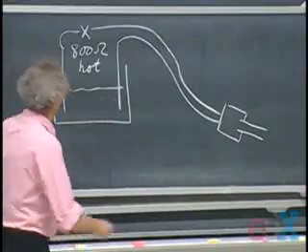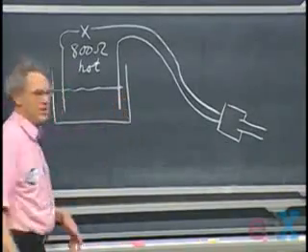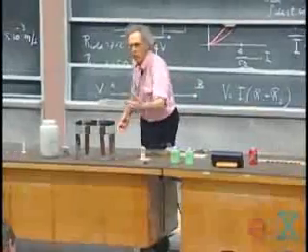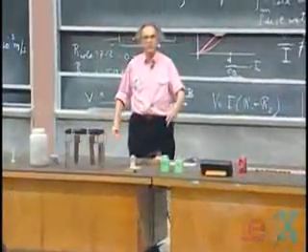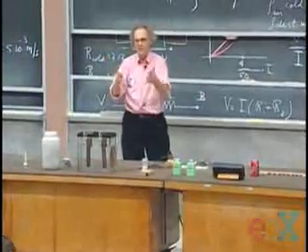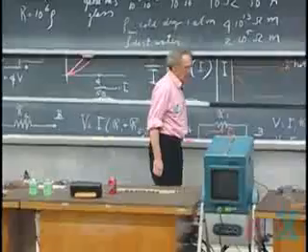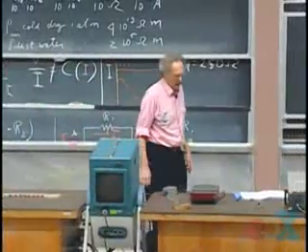You can calculate what this resistance is between the 2 plates. That's easy, you have all the tools now. If you know the distance, it's about 20 centimeters, and you know the surface area of the plate, because remember the resistance is inversely proportional with A, so you have to take that into account, and you take the resistivity of water into account. It's a trivial calculation.